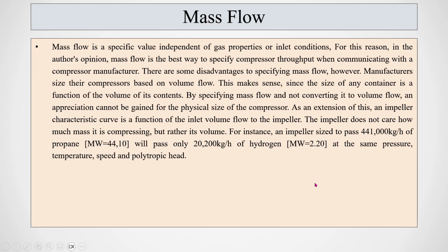Friends, I think I have covered all the topics. If you go through all the slides, your concept of the performance of a compressor will be clear. Changing the volumetric flow ratio, inlet pressure, outlet pressure, inlet temperature, outlet temperature, molecular weight, as well as the compressibility factor and specific heat ratio has a tremendous effect on the compressor. It is not like a pump and others. So you have to be very careful while running a compressor.